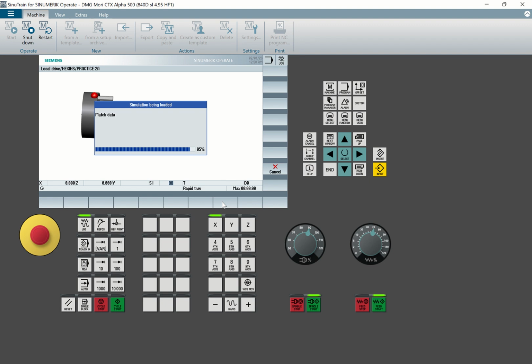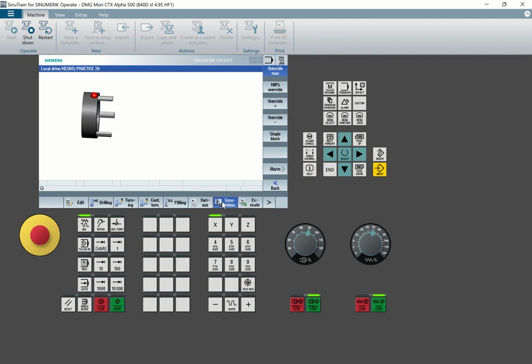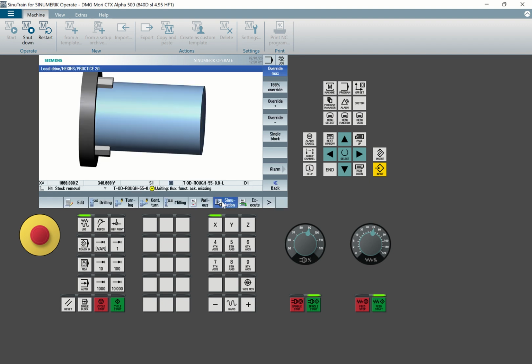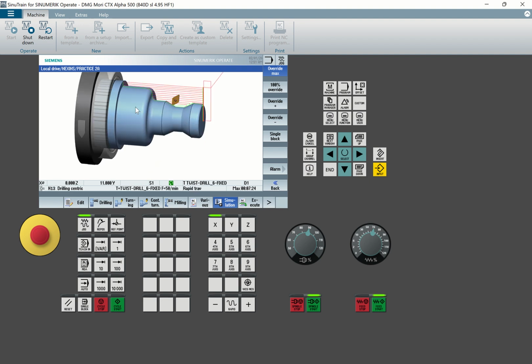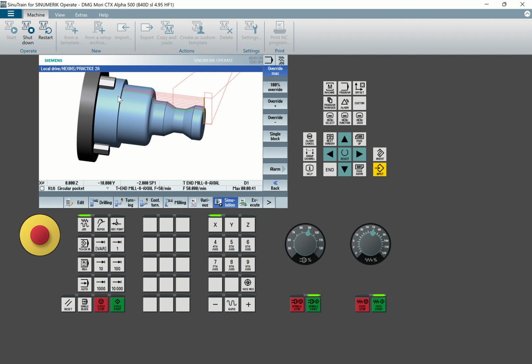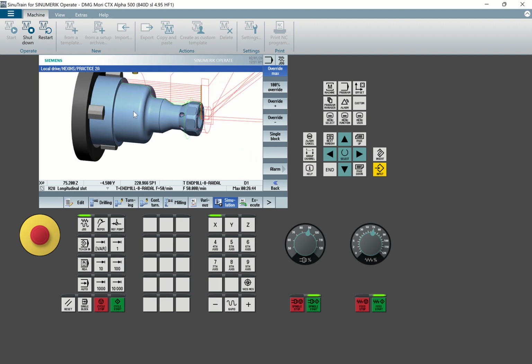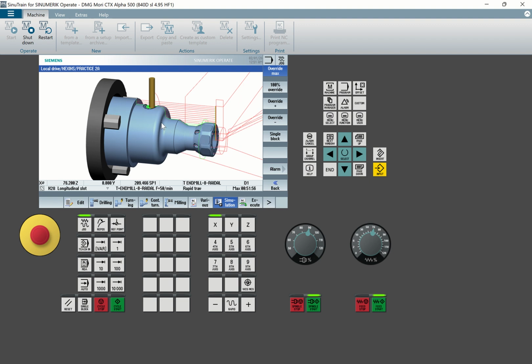But remember, you need to have a proper cutting off tool because the diameter is bigger. If the cutting length of the tool is not uniform or is not good enough to plunge the material, it will affect the output. So don't just program and then run the program on a machine without understanding the parameters or topology of your tool. It's very important to understand the topology of your tool so that you don't affect the output.